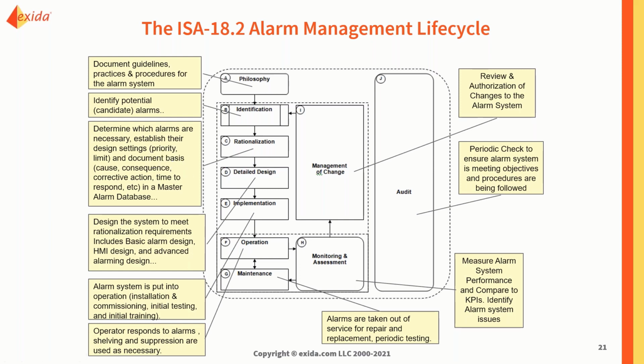And within the OPC standard, they have a data item called priority, and they also define it as a combination of the concepts of severity and response time. So priority isn't just about urgency. It's also a combination of the concept of urgency and the severity of the consequence that you're trying to deal with using this particular alarm. So by aligning that concept with the ISA 18.2 standard, you can actually use the OPC software in a better way.